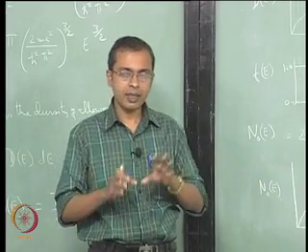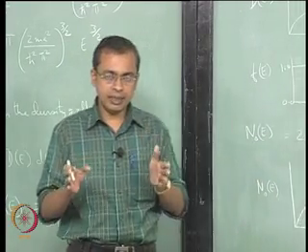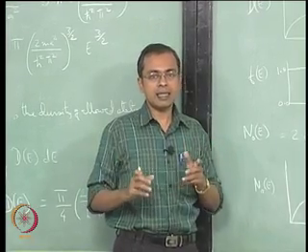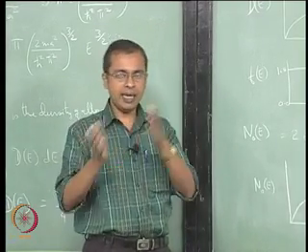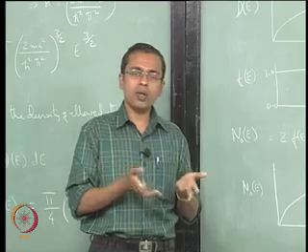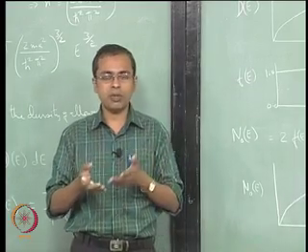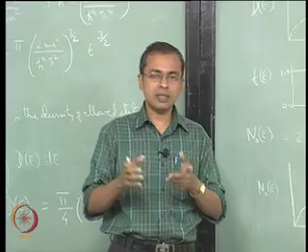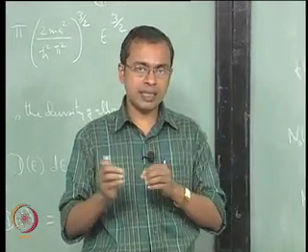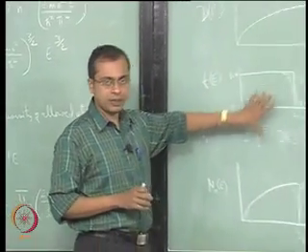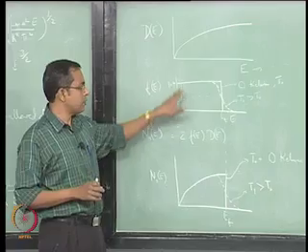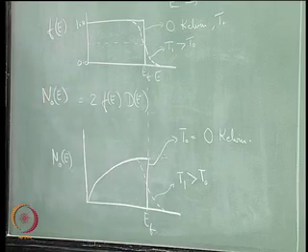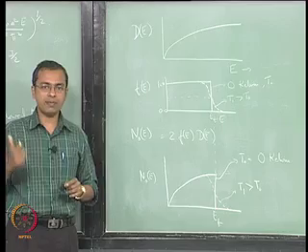Now in today's class we said that, given this situation, since there are relationships between E and k and E and n, you can plot this information in k space, you can plot this information in n space. And for our calculation purposes, where one of the things we were looking for is to add more detail to this picture, which is to find out the number of allowed states at each of these energy levels and therefore the density of allowed states, it is useful for us to start working with the n space.